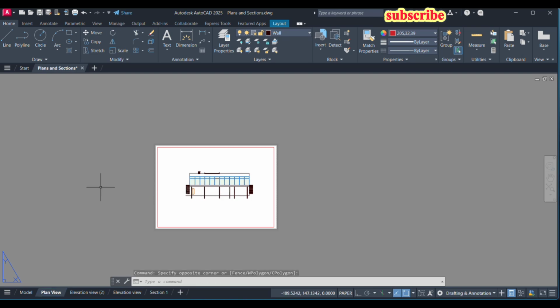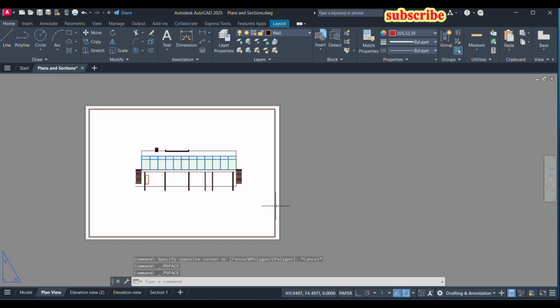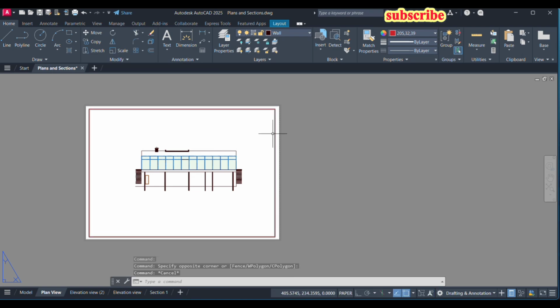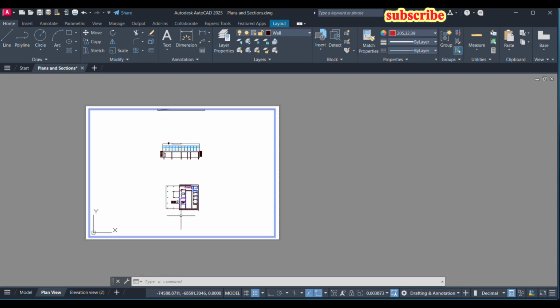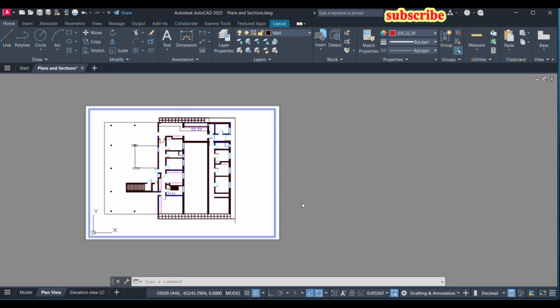And once we define the view name, we can double click inside this port view. We call this port view this rectangular red box. It defines the boundaries of the print area. So currently it is a side view, but we double click inside to scroll and search for our plan view. So this is the plan view that we want to print.